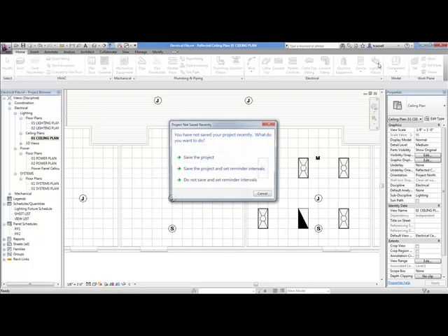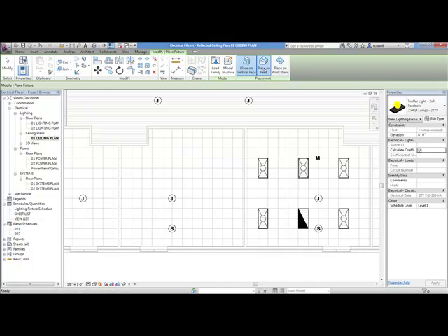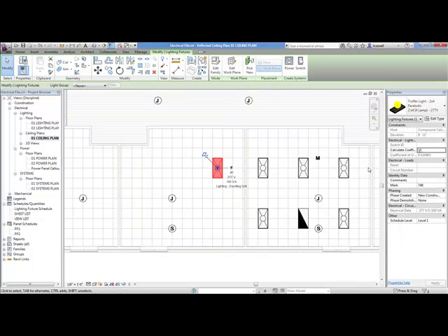So a brief start to what we'll be showing in a little while is in Revit MEP, when I want to place a light fixture, I'm placing a light fixture. I'm not placing a rectangle. That light fixture has information. Now Revit is database driven, and so when we add this information to the model and we go look at that, this model now knows that it has a light fixture that's a troffer light, and it knows that it's a 277 volt fixture with a load of 160.